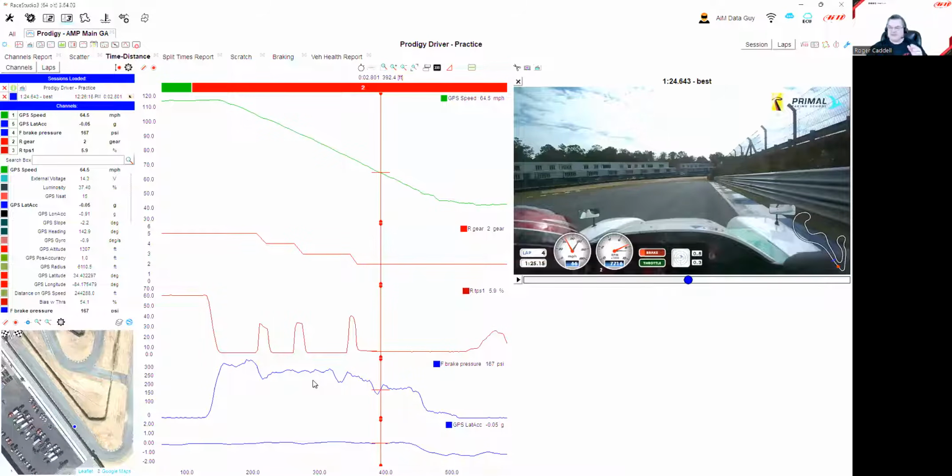Think about what throttle, steering, and brake, the driver inputs, do to the car. I always use my phone as the chassis, right? If the car is moving this direction and you hit the brakes, weight transfer happens. You load the front tires more.